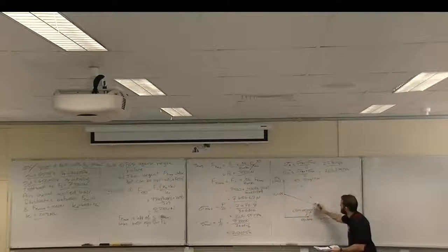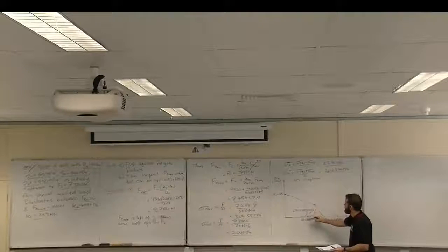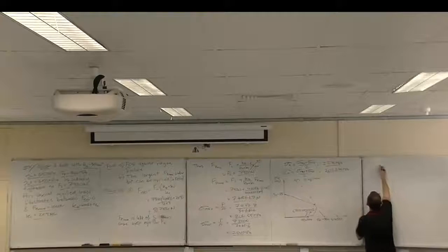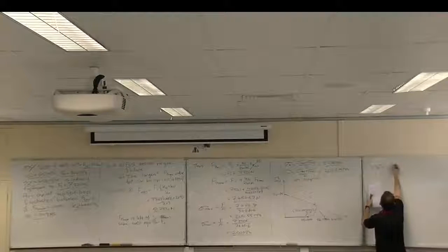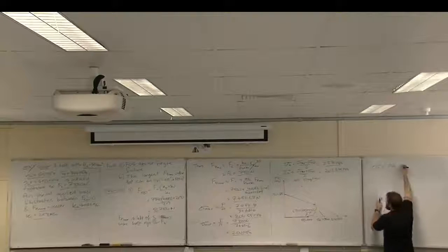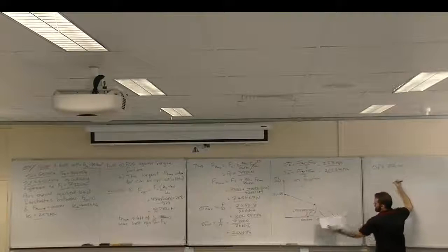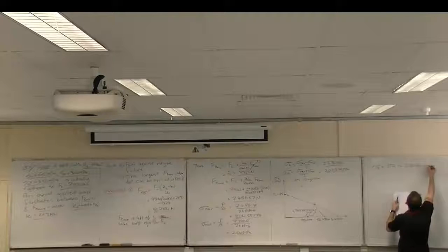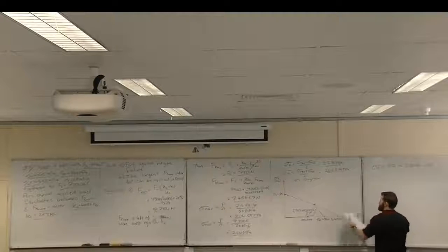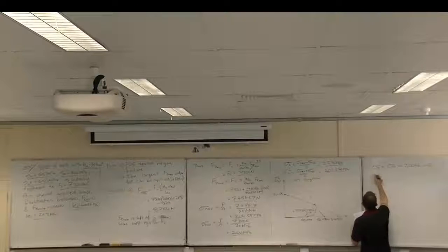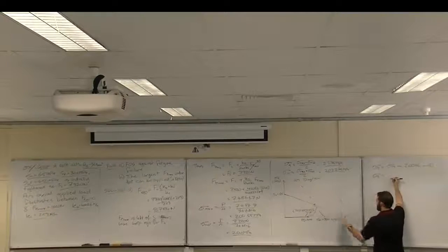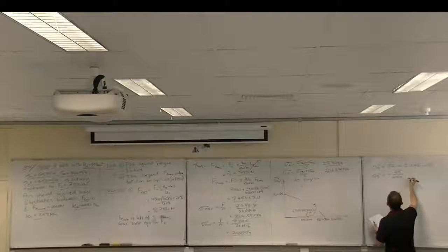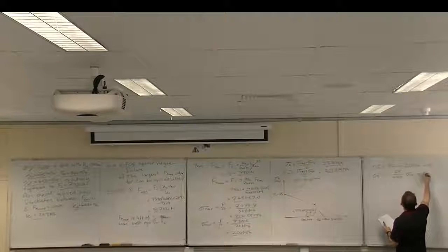So the equation to this line is its slope, which is 1, times x, which is sigma m, plus the intercept. The intercept is 200, so sigma A equals sigma m minus 200 megapascals, or 200 E6. And that's our first equation, the load line. And the second equation is the equation for this line, which is sigma A equals negative 65 on 450 sigma m plus 65.